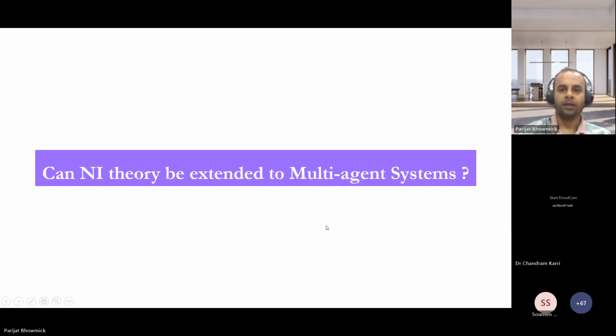Okay. So then the question is, we have already learned the basics of the NI theory, and now it is known to us that there is one class of LTI systems which is called negative imaginary systems, and what properties they satisfy. We have also come to know their stability result, and the stability condition simply depends on the DC loop gain. That is the reason why it can be applicable in many systems where only the DC gain measurement will make the system possible to work in practice. In such kinds of cases, this theory can really become useful.